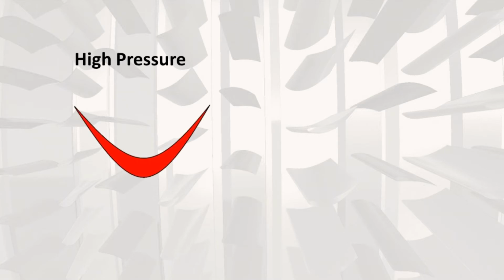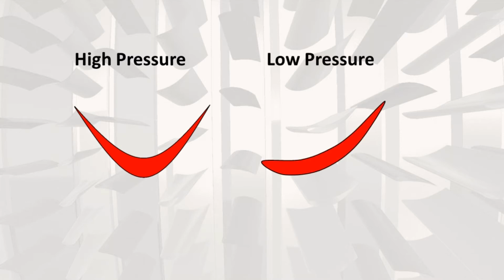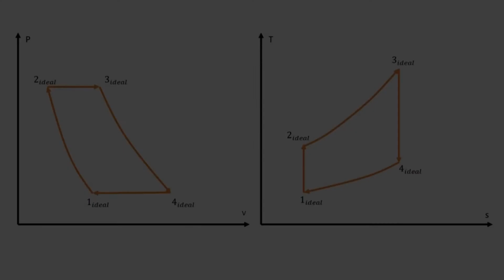The chosen design varies from stage to stage, as the high pressure stages at the inlet of the turbine are normally of the impulse design in order to extract maximum energy at high RPM. The successive low pressure stages are of reaction type in order to extract energy at maximum efficiency at lower RPMs.